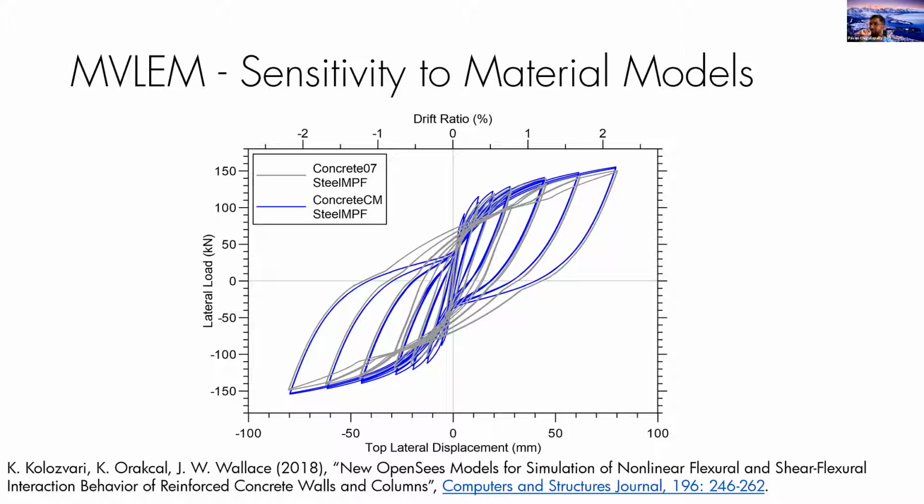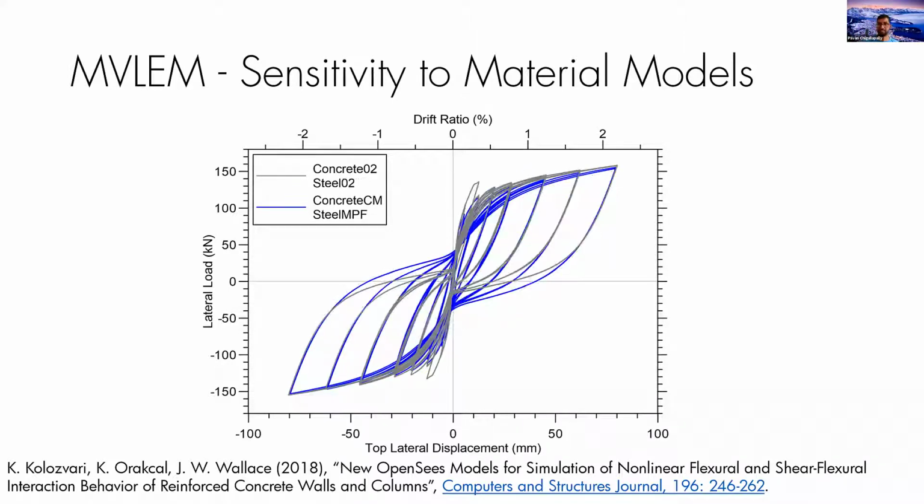Okay. So maybe there's a way to manipulate or calibrate a little better or something like that. Because I do get that high initial stiffness which you are showing in Concrete02, so that's why I was asking. Yeah, Concrete02 is an issue, and you don't have control over the initial modulus of elasticity, right? Yes. And if you have a high strength concrete, then that drops a lot because of that parabolic curve. But yeah, someone could implement a Concrete02 version with the initial stiffness. That'll be helpful, and it would be a pretty easy thing to do actually.